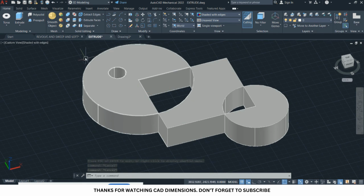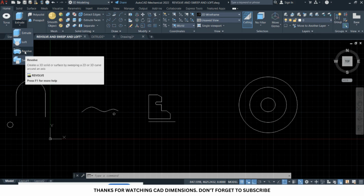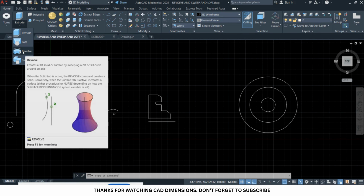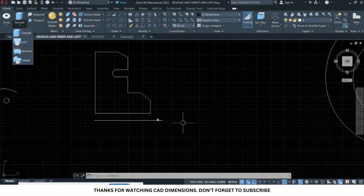Alright guys, let's move to the next tool, and that has to do with the revolve, the sweep, and I think we have the loft. So we're going to start first of all with the revolve. All right. So the revolve is when you have a shape and you want to create a revolve around a particular axis. So I'm going to use this third sketch here to show you how to revolve. Now, this is the sketch and this is the axis that I want to revolve around.